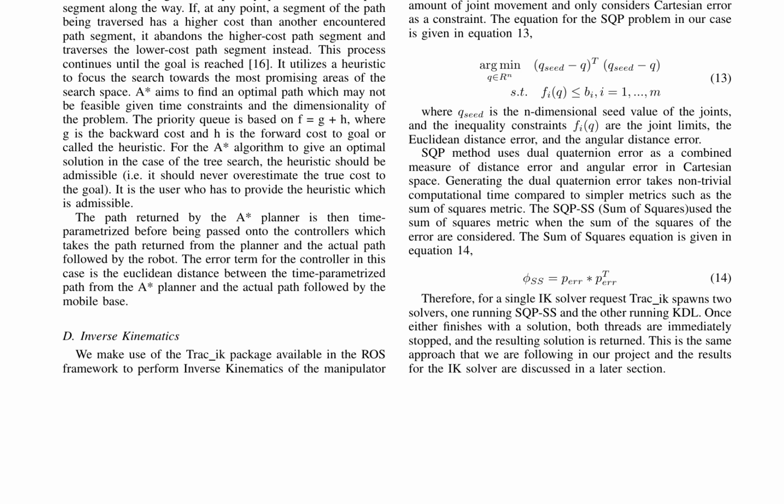For the manipulator, planning is executed in joint space, considering joint limit constraints to avoid the need for inverse kinematics at each planning instant. This approach saves considerable time and avoids the complexity of obtaining correct joint angles from multiple inverse kinematic solutions. Position, velocity, and acceleration profiles for one of the joints are shown in figures 10 and 11, with similar profiles obtained for all joints. Quintic polynomial planning is employed to minimize jerkiness in the system.